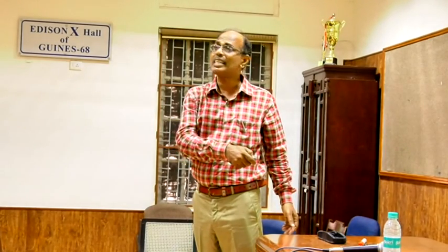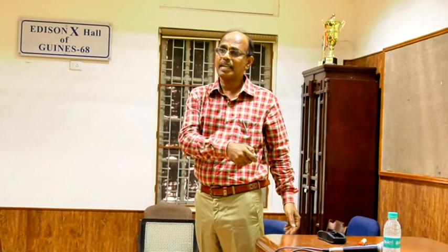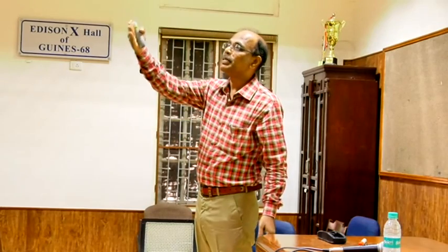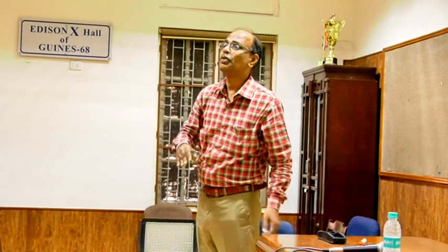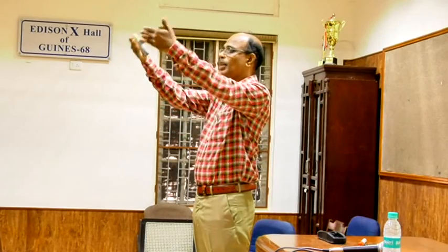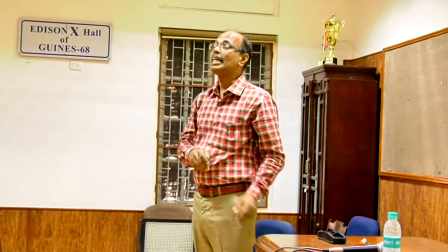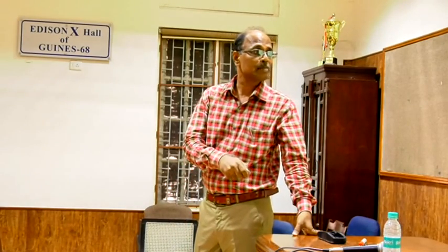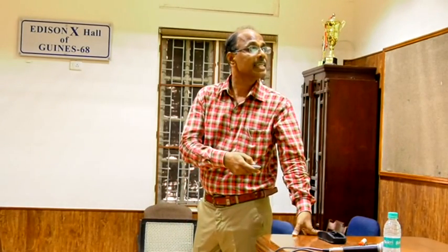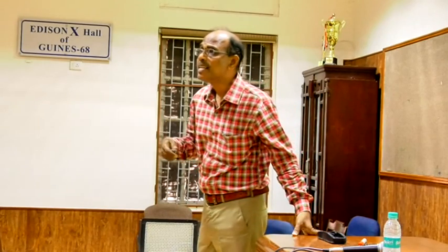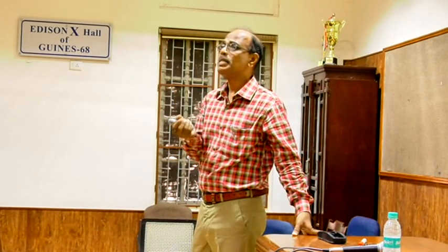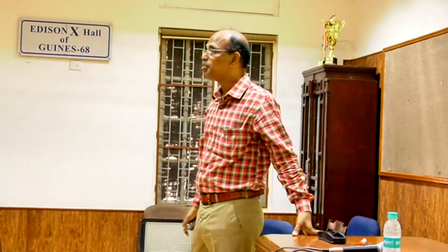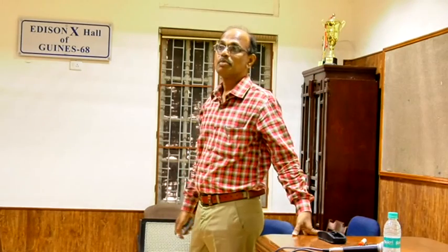So this V and V get cancelled, but because of this addition, the whole matrix is symmetrical, and the upper half will be the mirror image of the lower half. So we can simply calculate the upper half, and the lower half can be simply copied. That drastically reduces the computation time. This is the mismatch vector, and this equation is repeatedly solved. We have to assume a starting value of P and delta. If not available, all voltages are assumed to be 1 per unit and angles are assumed to be 0.